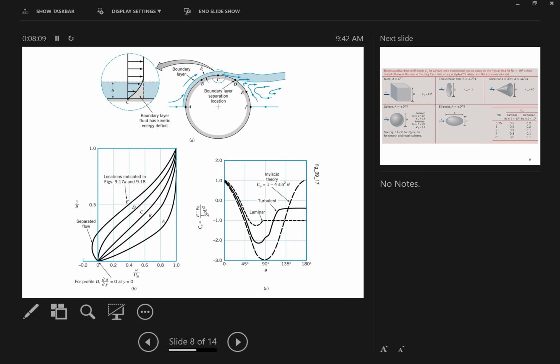Think about when you're running really fast down the hallway and trying to make a curve or a bend. You don't quite make it if you're running too fast, but if you're going slow enough, you can. This is exactly what's happening here. The flow is going around here, gets to a certain point, can't make this bend because it's now a sharp bend, and boom, it becomes detached. That's where you get those wake regions, and we'll talk more about this. This is what they call flow separation.